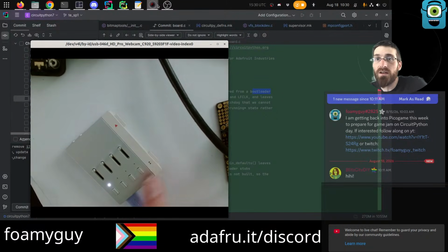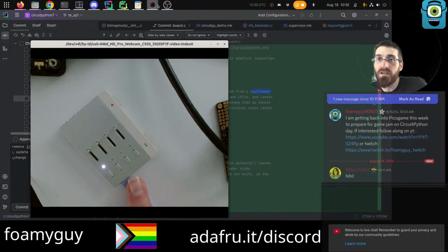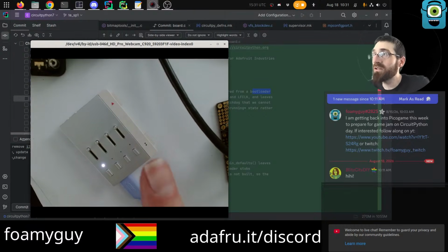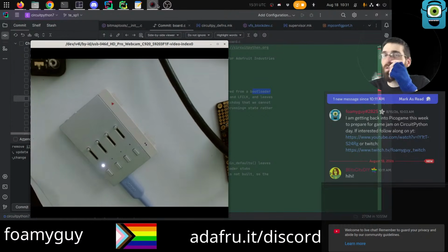So you hold those outer two buttons while you plug it in. Plugging it in turns it on, which launches the bootloader. The bootloader checks for those two buttons to be held for, I think, maybe 2 seconds or something like that. And if they are, it will launch you into the actual bootloader that lets you overwrite the application firmware.